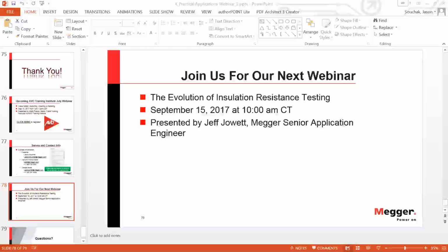to grow through the insulation. And if you look at the growth rates, which are about 10 millimeter per hour, and you look at the typical insulation thicknesses for medium voltage cable, then you can see why an hour period is a good time to accomplish this. And there's some more information about this in our previous webinar about VLF testing.